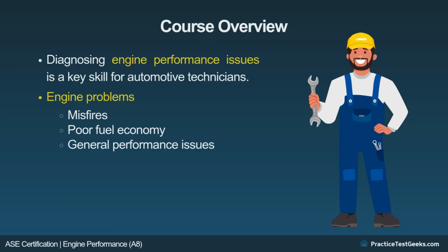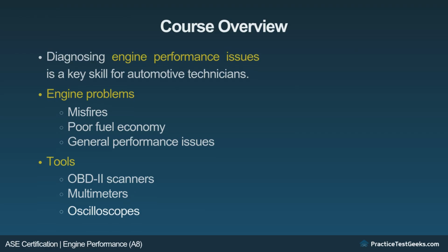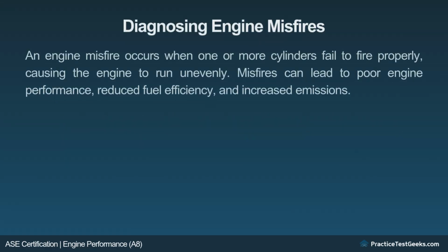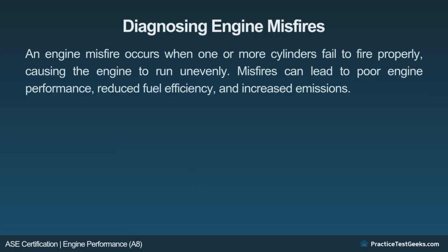Additionally, learners will be introduced to the tools required for in-depth engine performance analysis, such as OBD2 scanners, multimeters, and oscilloscopes. Diagnosing engine misfires. An engine misfire occurs when one or more cylinders fail to fire properly, causing the engine to run unevenly. Misfires can lead to poor engine performance, reduced fuel efficiency, and increased emissions.